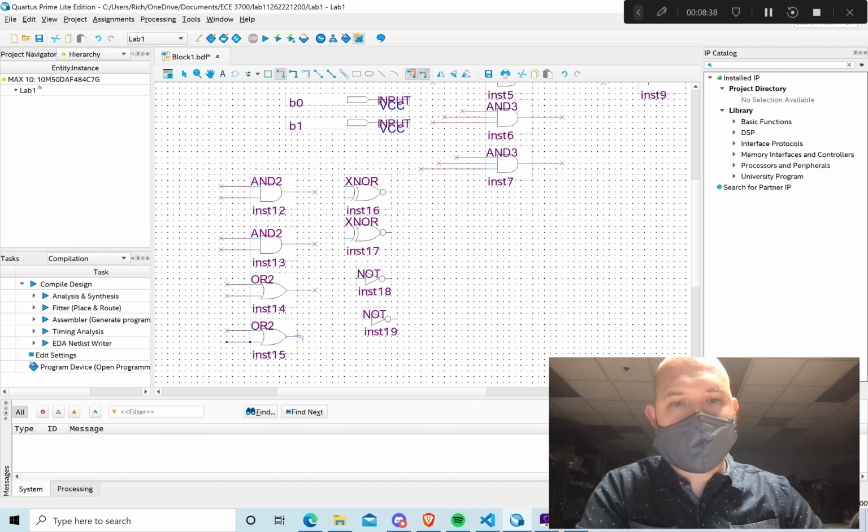So this one is A1. This one is B1. And again, just to reiterate probably the third time, the reason why that is the case is because these are my inputs, A0, A1, B0, B1. So when I name these the same thing, they become physically connected. Okay, so my output over here, per my naming convention, I'm going to name I00, F1, because this will be the F1 when I is 0, 0.